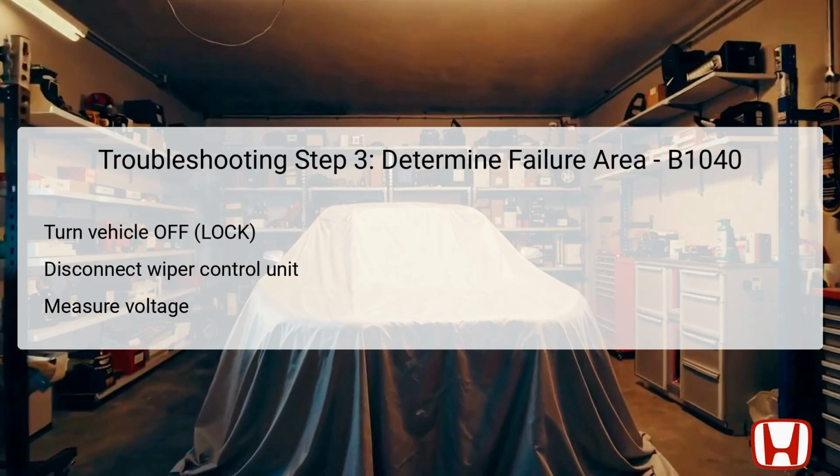With the vehicle in this mode and the connector disconnected, measure voltage between test points 1 and 2 using a multimeter. Test point 1 connects to pin number 2 of the wiper control unit, while test point 2 connects to pin number 1. If there is battery voltage present, it indicates that power is reaching the control unit and the issue lies elsewhere. Conversely, if there is no battery voltage, further investigation is required down the wiring path.